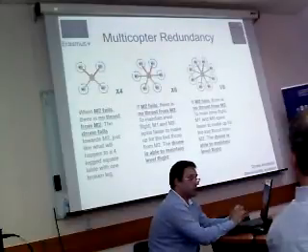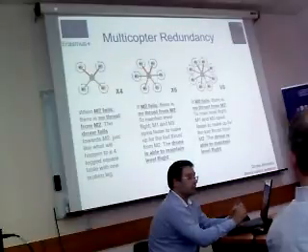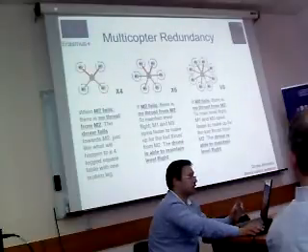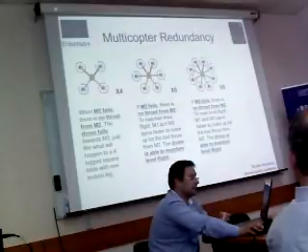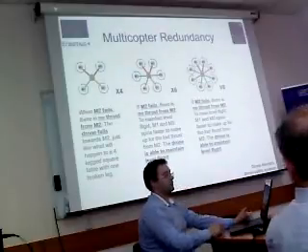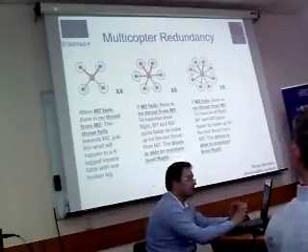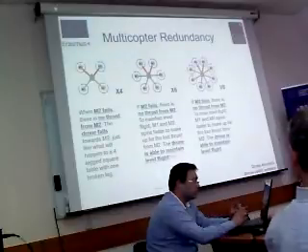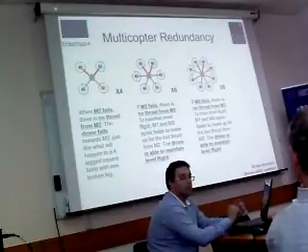So the propeller is attached to a motor which spins either anti-clockwise or clockwise. So this creates thrust, but also a clockwise or anti-clockwise moment. So in simple terms, the moment is a measure of the tendency to cause a body to rotate about a specific point or axis. So the moment created will be in the opposite direction of the propeller spin direction.